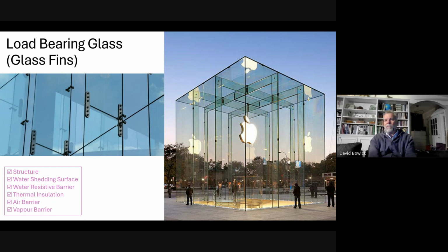Maybe this is worth saying actually. The thing you don't see in a window are the setting blocks for the glass. You have a great big window frame all the way around. You might be inclined to think that the glass is continuously supported on the bottom. In fact, the glass sits on 2 points in the 2 corners, 2 little hard rubber blocks in the corners. And in plane, the glass spans to the corners of the frame. The frame is not carrying the weight of the glass, or it is, but only just in the corners. But the frame is carrying the wind load.